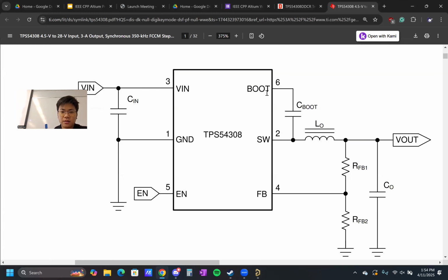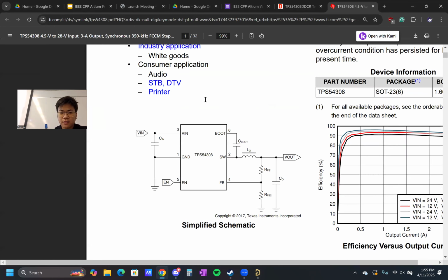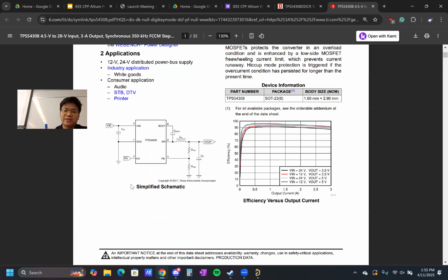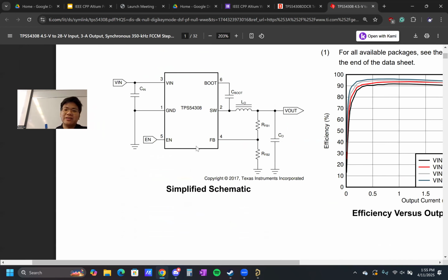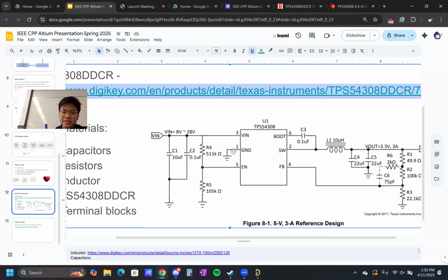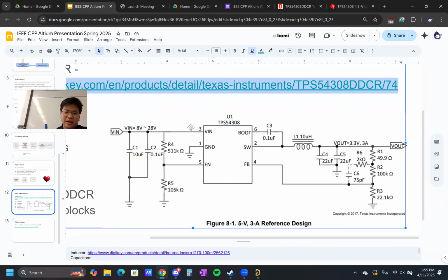Go ahead. Talking more about our actual circuit itself, for those who are curious and maybe don't know how one of these works: what it essentially does is it takes in an input and switches from that voltage to ground very quickly. And then you can say that the average voltage is 5 volts. Now the thing is, your electronic components don't like that, right? They don't like 28 volts and 0 volts over and over again.